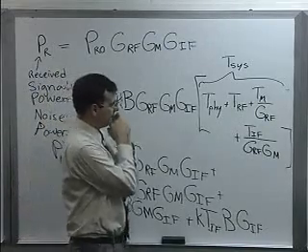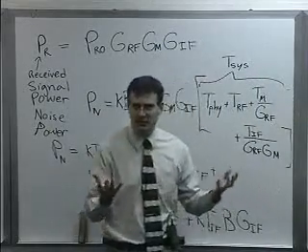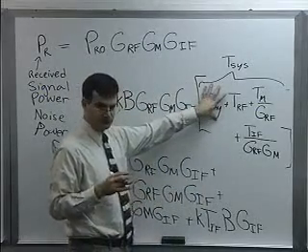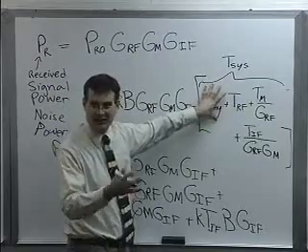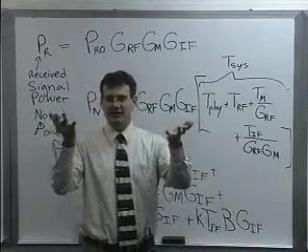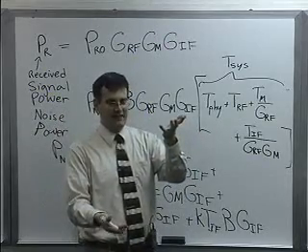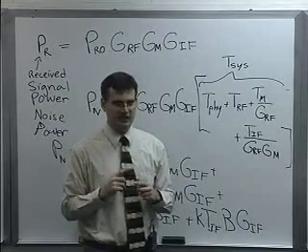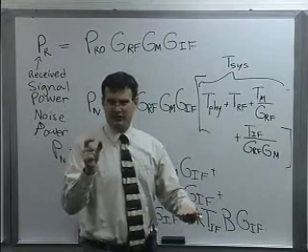Now, in this class, unless I tell you otherwise, this is an engineering class, so we're very into being practical, right? When you're speccing out a receiver, one of the reasons why we use an LNA instead of just an A on the very front end is because that's where it's critical to clean up your signal and give it the highest possible gain you can and add the least amount of noise. And in fact, adding the least amount of noise is even more critical than the gain, which is why most LNAs, if you buy them, will have lower than average amplifier gains in that block of amplification.